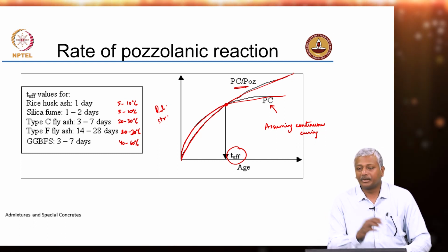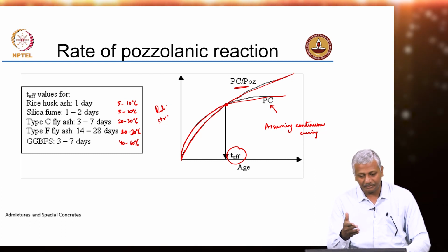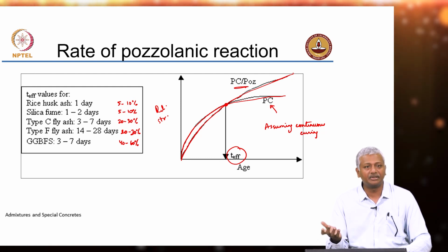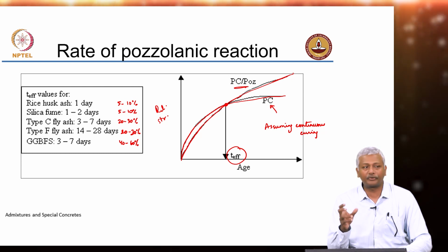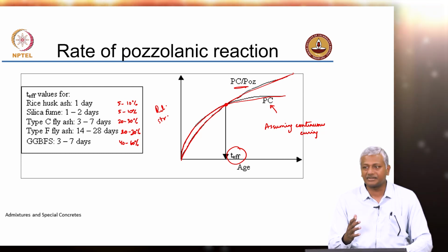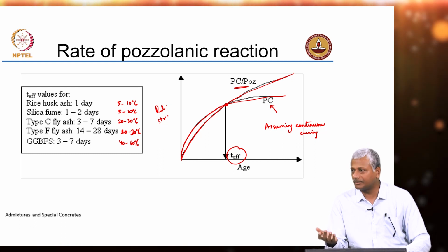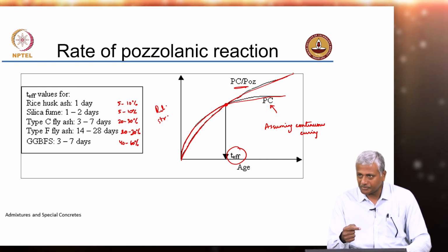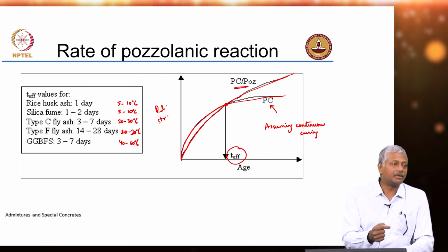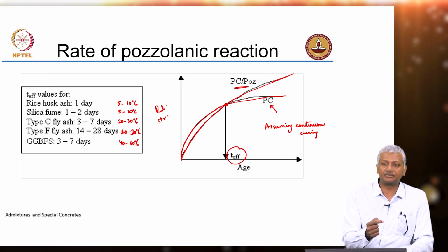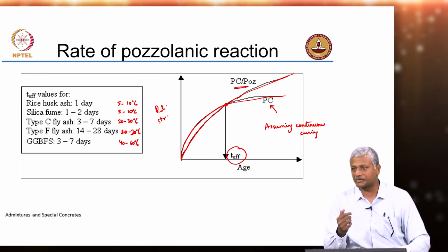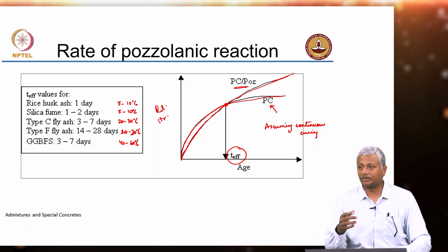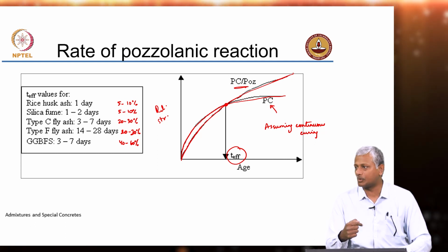So, the very issue that leads to a slower reaction, Pozzolanic reaction being slower as compared to hydration reaction, that is the primary reason for Pozzolanic concrete having a lower heat of hydration, and that has its own advantages, less thermal cracking, right, better long term performance and so on. Unfortunately, because of that reason alone, that means because of the low rate of strength development alone, a lot of the initial phase trials with Pozzolanic cement were rejected by customers because they felt that the concrete was not getting strength fast enough, or the concrete strength was getting compromised because the cement is slower reacting.